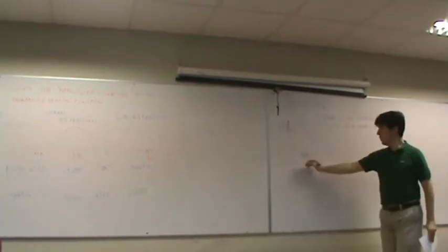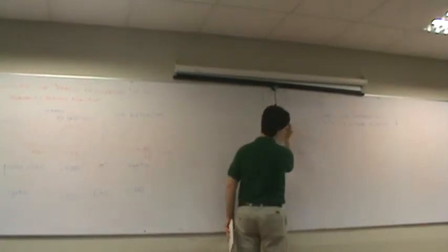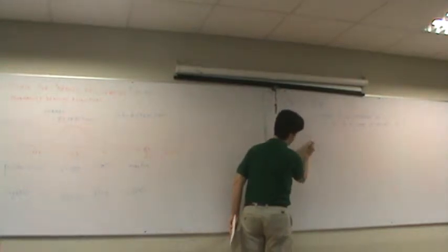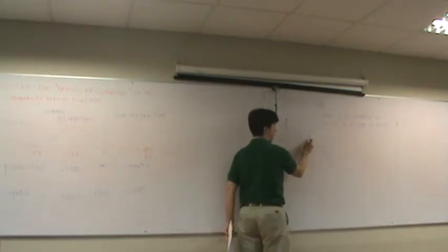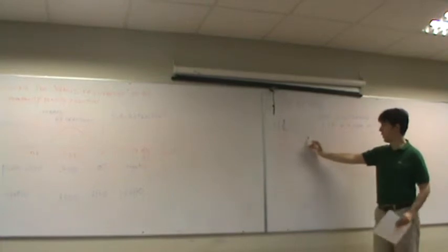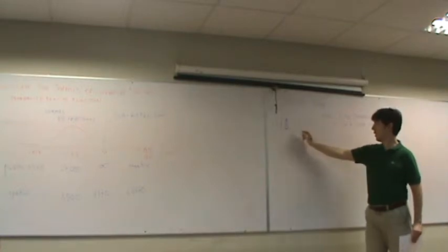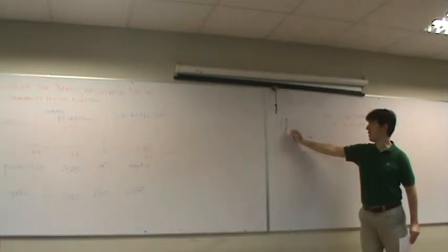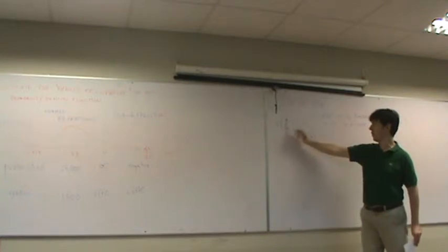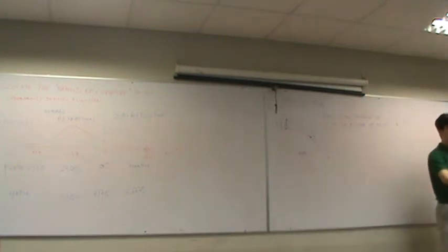Well, if we use the equivalent earth radius, the coverage will be clearly given by the tangent point. So any point from the tower to this point here that I indicate as XA, from 0, any point whose distance on the ground is from 0 to XA is visible from the tower.